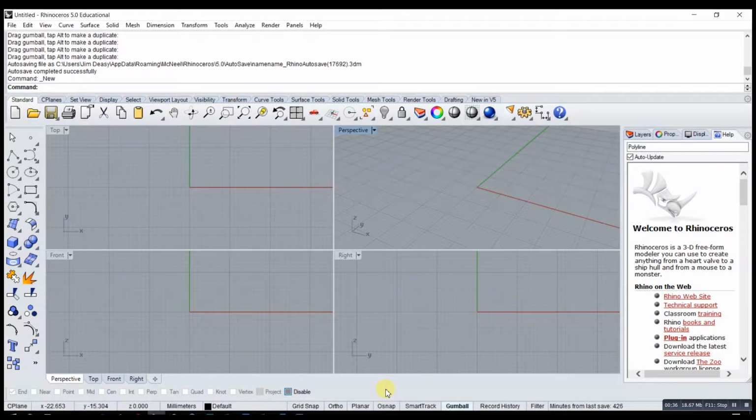So in this video, I just want to talk a little bit about navigating 3D space in Rhino, and understanding what these four viewports are here, okay? The one to pay attention to most is the upper right hand one here. That's your perspective view. If you click in this box with your right mouse button and toggle around, you can play around in 3D space and see your work area. If you roll your middle mouse button out, you can see the grid that you're working with. This is kind of like your ground plane or your work area.